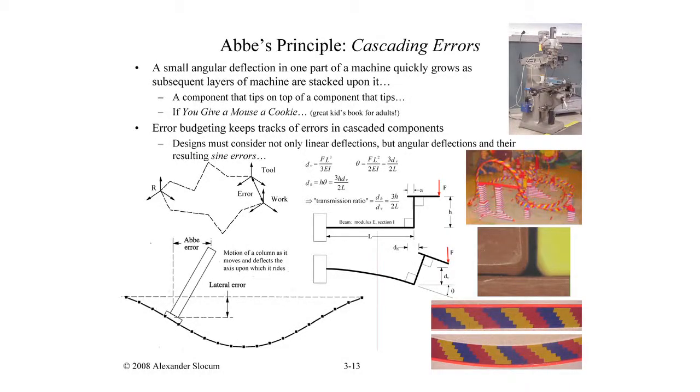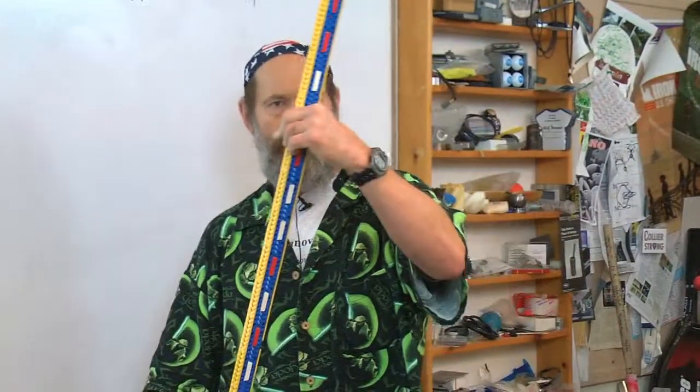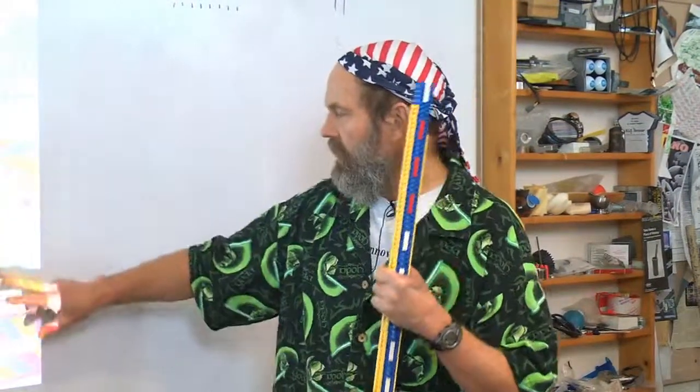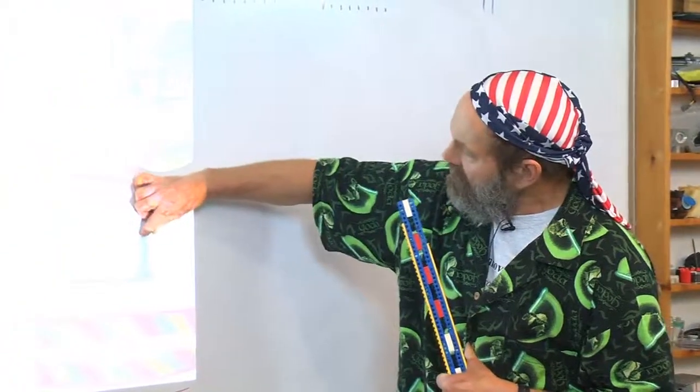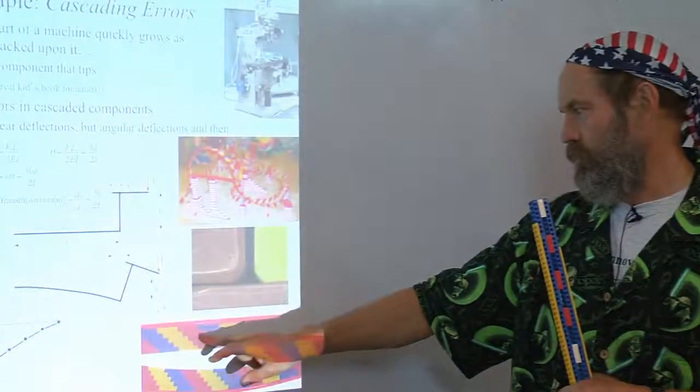Let's have some fun with this now. Everybody knows that plastic toy blocks, for example, Legos, are very, very high precision. You put them together wonderfully, and you make nice straight beams and good things, right? Well, it turns out that in order to actually manufacture them and use them, you've got to have small little gaps between things. You've got to have little spaces, because if they were exact, and due to uncertainty in manufacturing, even by 1 micron, if you design them to be exact and they were a little bit too big, they wouldn't go together. So you leave a little bit of spaces to make this nice, straight, beautiful wall.